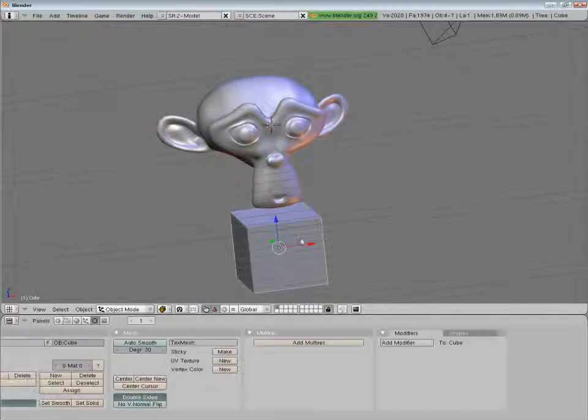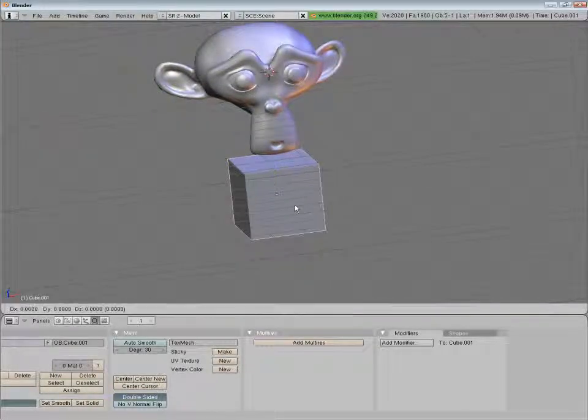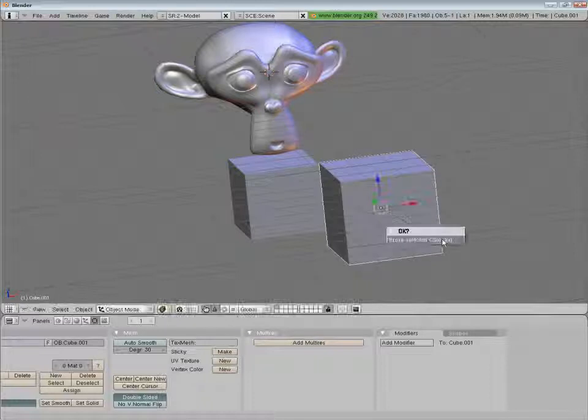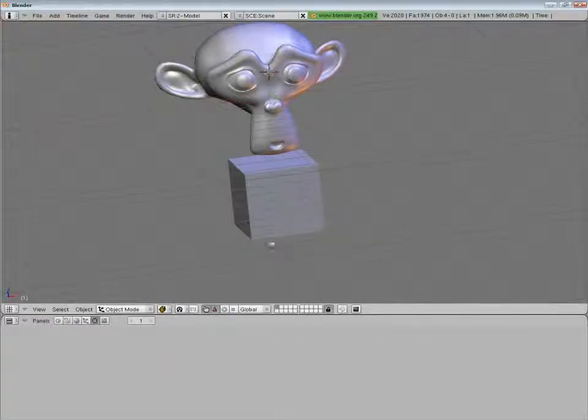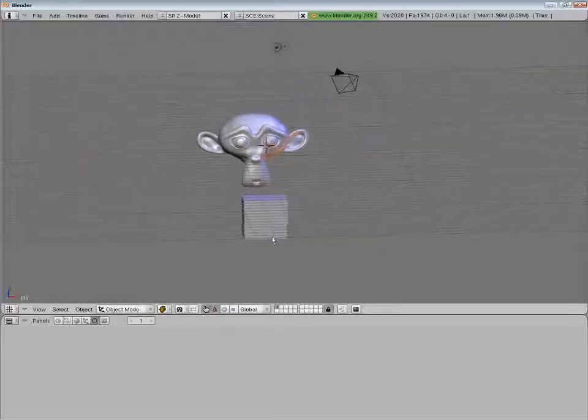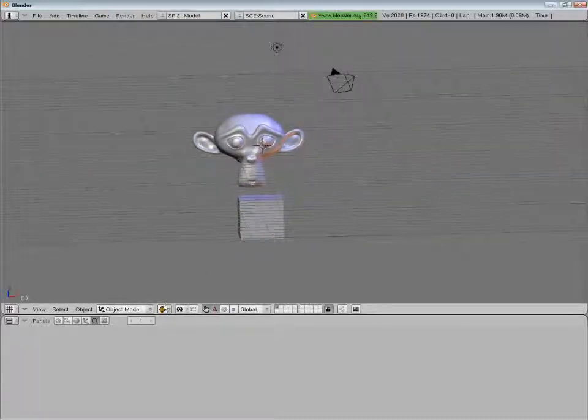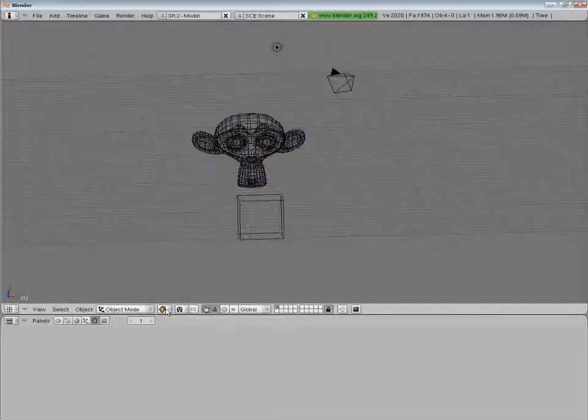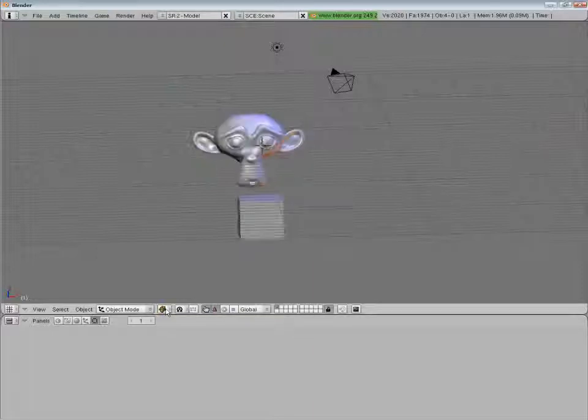If you press escape after duplicating, that is after Shift D, the new or duplicated object will be sharing the same space with the original object. Then we can grab and move it anywhere later, or rotate or scale. Another useful hotkey is the Z key. This flips through the object view mode from transparent to solid, from wireframe to solid.